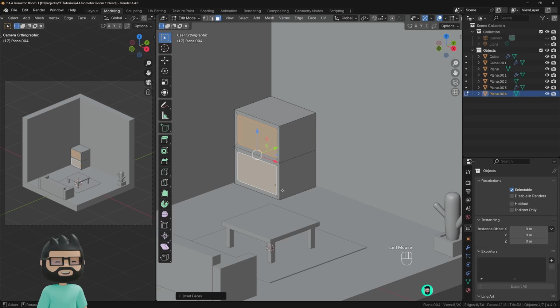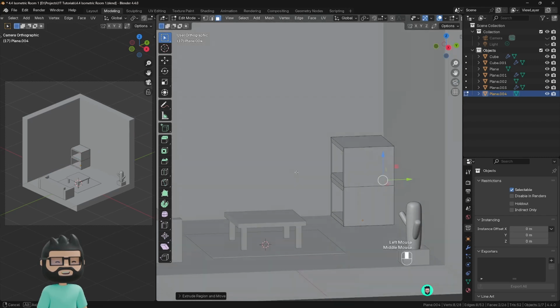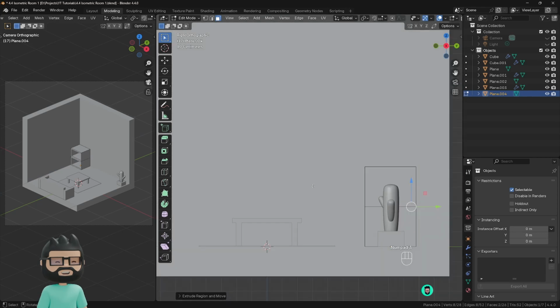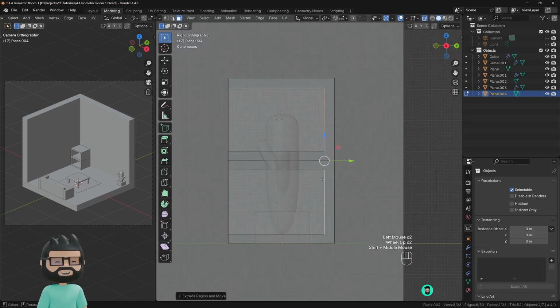and while the faces are selected, press E to extrude and move your mouse backwards and just place it by left clicking. Now you cannot see how much inside or in depth are these, so we can go into the right view mode and enable X-ray mode again, and now you will notice that these are this much, which is fairly accurate.